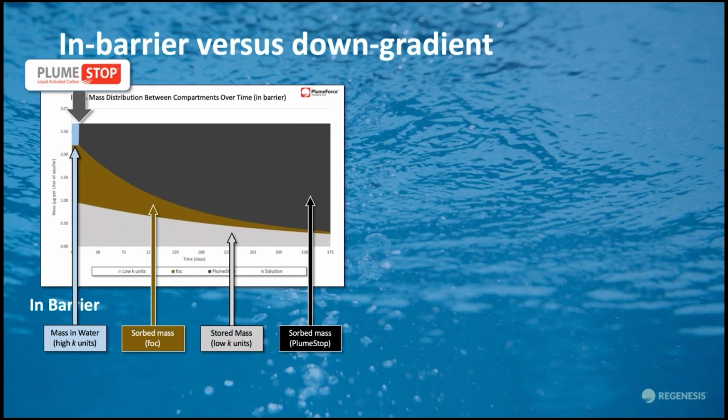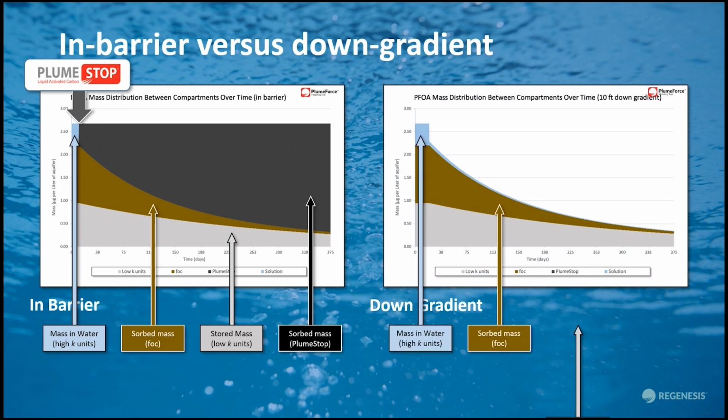Importantly, as the sorbed mass on the carbon increases as it loads up with back diffusing and desorbing mass, competitive interactions between sorbing contaminants can lead to degrees of displacement for the weaker sorbing species that initially were captured, as we'll see shortly.